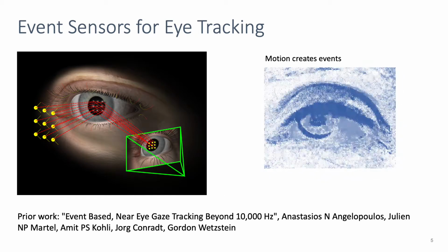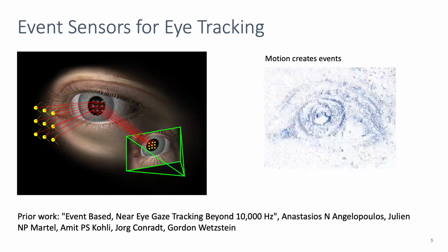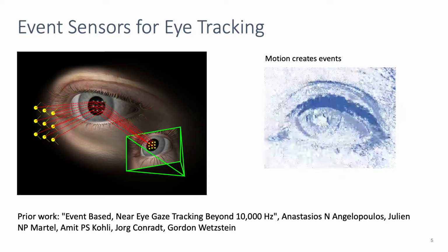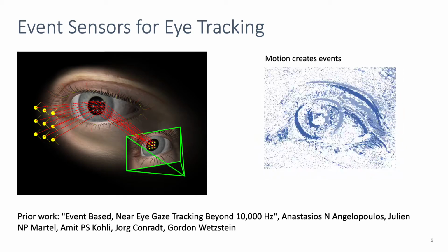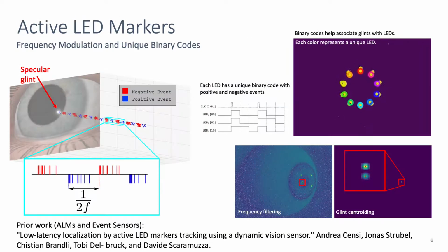Our method does not require camera frames, instead using the light sources actively to stimulate the event sensor and produce a robust signal. We flash our LEDs in a high-frequency binary pattern. Ones and zeros are encoded as 300 and 600 microsecond pulses respectively. Using a rolling window, this gives us a 1 kHz update frequency.